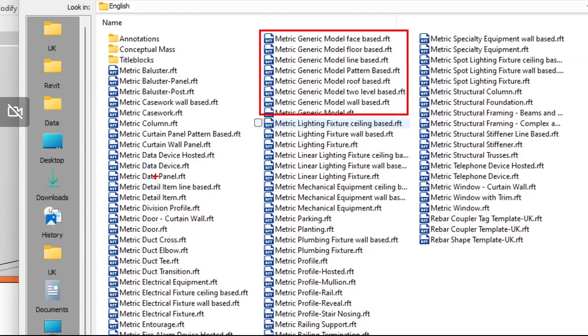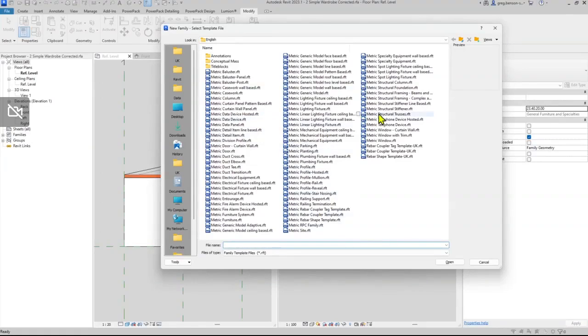So my recommendation here is, if you're using one of the more specific families, just draw a simple extrusion, load it into the project, and test it. Make sure that it has got the innate behavior patterns that you need from the family that you are creating, okay? Because you can't change its category. However, with the generic ones, you could actually start off with a generic model and then you can change its category. And the category, of course, aligns and is used when you create your schedules.